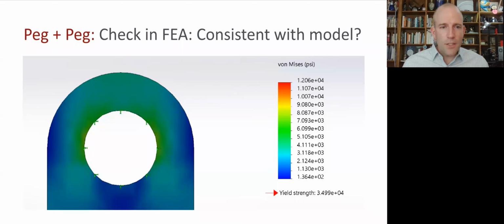All right, so what we see is we have the stress is varying across the cross-section, and that means there must be some bending happening. Yeah, but the stress is not lowest in the middle, and that means there's substantial combined loading. And this is very similar to what we saw in a previous example, where we have tensile stress from bending over here and a tensile stress from the axial loading, and they're adding together, we're getting a higher stress. And on this side, we're getting a compressive component from the bending. It's canceling with the axial tension. And so we have this high stress on the inner edge and a low stress on the outer surface.